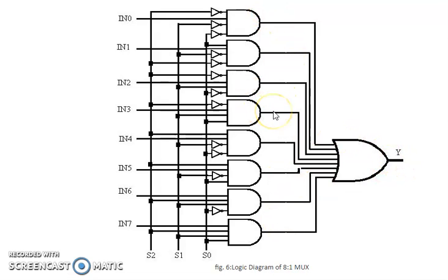If the fourth AND gate is 1 and the rest are all 0, our output will be 1. So whichever one is enabled, that content is what we are going to get across our final output. Now, in order to select one out of these 8, how are we going to do that based on these select inputs?